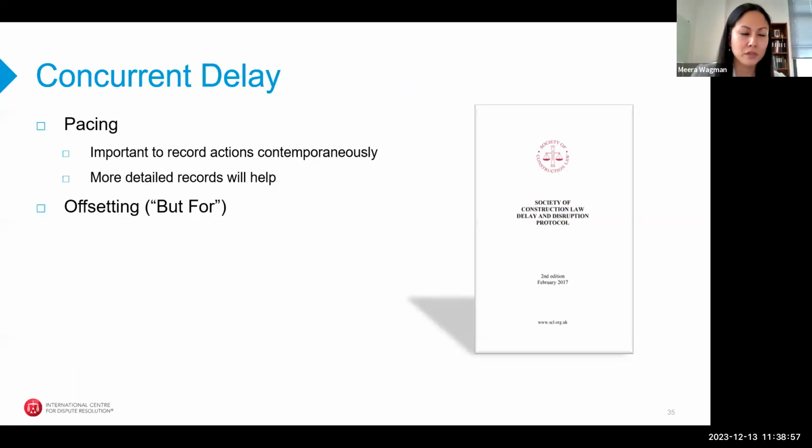Thank you, Emily. So just a couple other points, and I think Emily touched on this, but concurrent delay really is a hotly debated topic. It is just viewed by many different parties in many different ways, as Emily explained. Two delays that happen at the same time do not necessarily constitute concurrent delay as it relates to an impact of the critical path and either relief of liquidated damages or success in achieving a compensable delay claim and getting damages paid to the contractor by the owner.